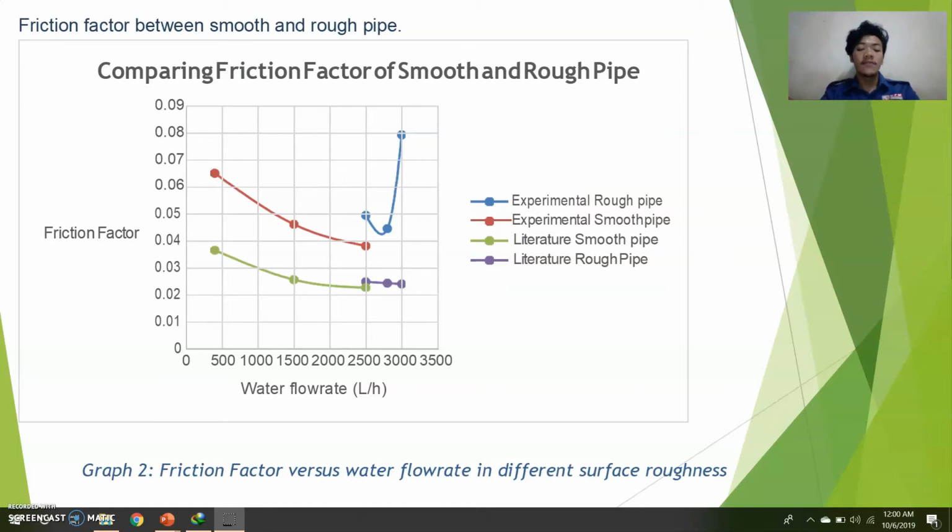According to Bernoulli's principle, the sum of the pressure head, the velocity head, and the elevation head is constant along a streamline. This equation is only valid for steady, frictionless, incompressible, inviscid flow, and considers that all energy is conserved.